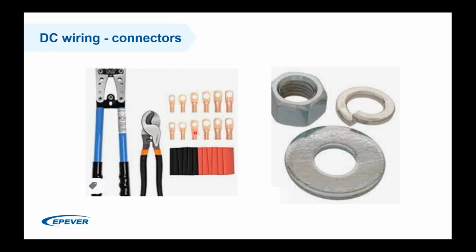And yeah, we have seen a lot of failures in the field because of this problem. So the tools that we are using for pressing the lock to the cable and the amount of the insulation, making it water and moisture resistant, is also very important. If you do not cover it by the shrinks, then in time the cables will corrode, and this corrosion will increase the resistance again, and then it will get hot. So even very small parts of your installation will matter.